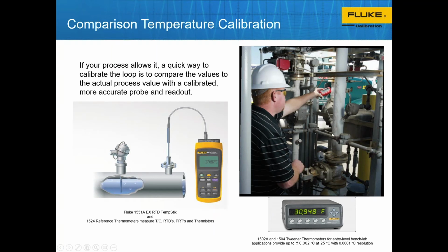I do want to point out something really quick here. We're going to talk about something called stem conduction. And this is an example where perhaps this person is using this probe and it's accurate enough for them, but there are significant errors with the heat or whatever's in here conducting up the stem and radiating away and being a source of cooling to the actual process. But we'll talk more about that later.